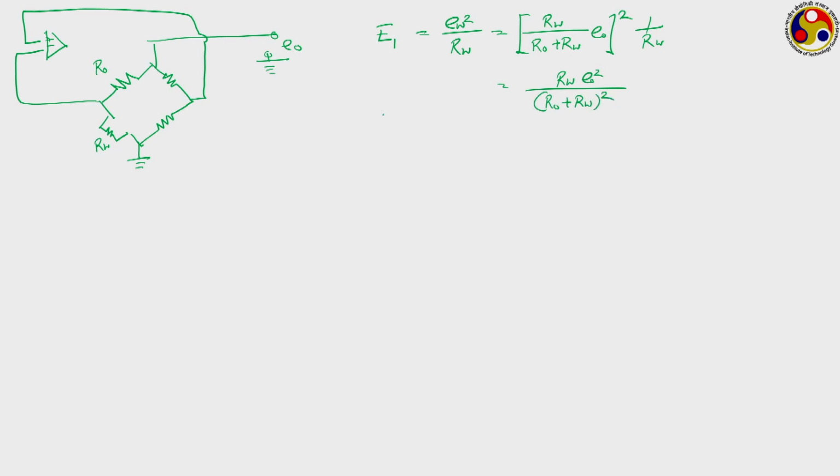And how much is the current that has power, rather energy, that has been withdrawn by the film or the flowing fluid? That has to be the area of the film into H into (TW minus TF), where AW refers to the surface area of the wire or your probe, H is the heat transfer coefficient, TW is the surface temperature of the probe, and TF is the fluid temperature, and these two have to be equal to each other.